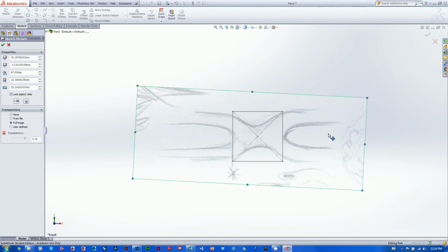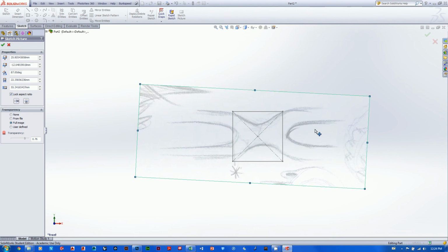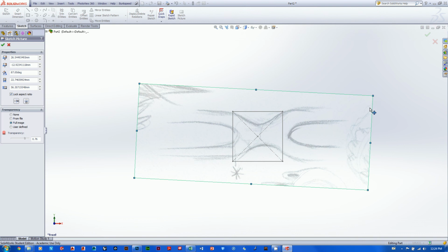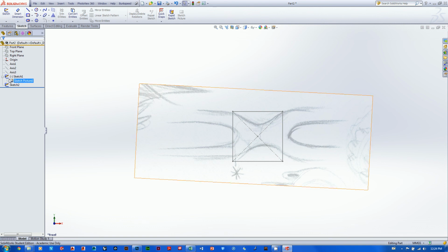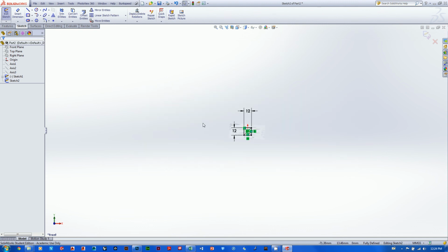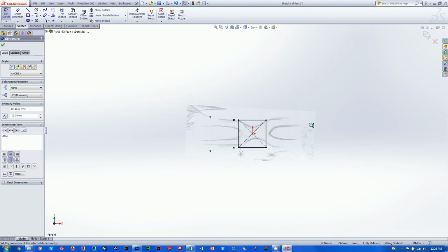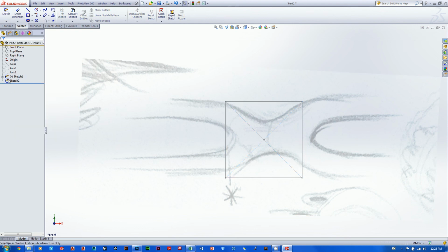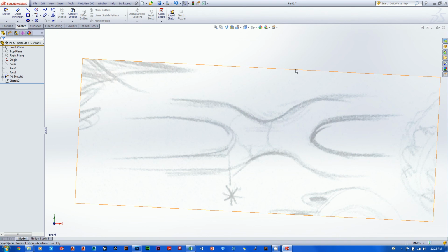Don't forget, SolidWorks is going to handle all the precision, so this sketch doesn't need to actually be that precisely sized. We just need to make sure it's telling us the information we need to get our design down. Okay? All right, that looks about right, and so now I'm happy with that, and I'm going to hit the green checkbox and confirm, and I'm a happy camper. Great. I've got this sketch here with my dimensions on it, 12 by 12. I've got my sketch placed into the document, and now I am ready to start making a sketch. Now that I know that this sketch picture is the right size, 12 by 12, I'm going to go ahead and just hide this rectangle with my dimensions on it because I don't need to look at it anymore. Not edit sketch, excuse me. I have to hide sketch. Okay, good. There we go.